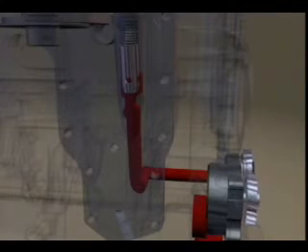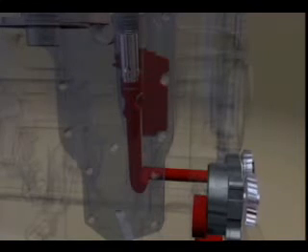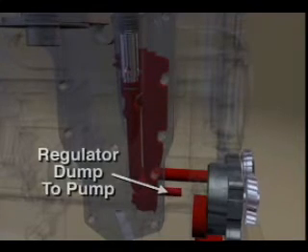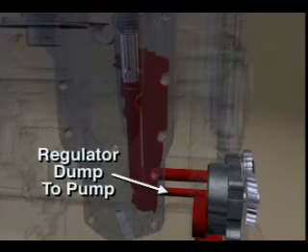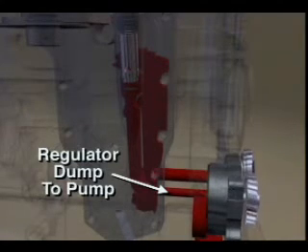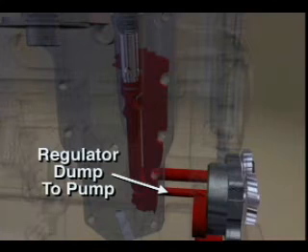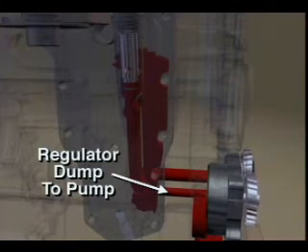When the oil pressure from the pump exceeds the pressure regulator opening pressure, the valve opens, uncovering the dump port and allowing some oil to drain back to the inlet side of the oil pump. Recirculating the oil back to the pump increases the supply of oil to the pump. This circuit assures a constant oil supply without cavitation at high engine speeds.